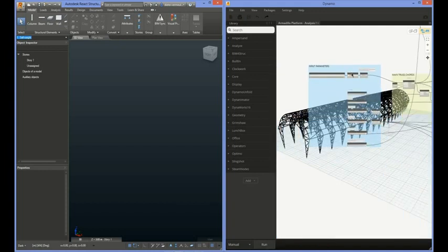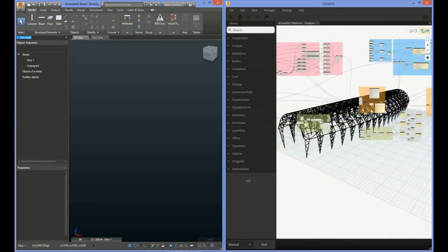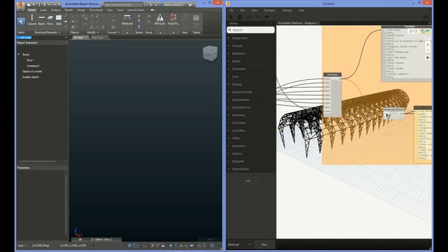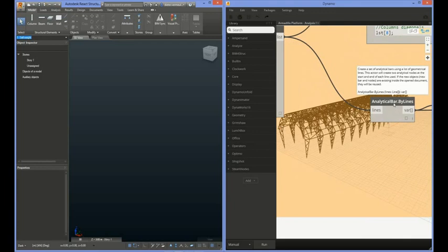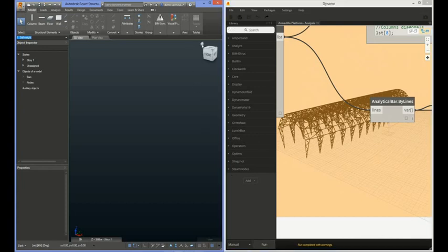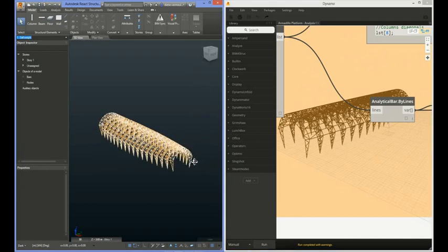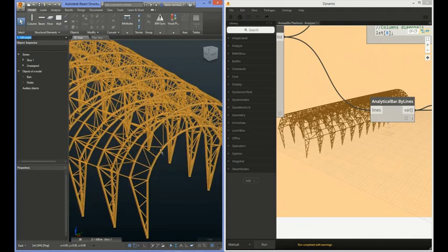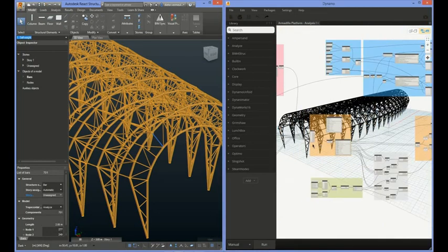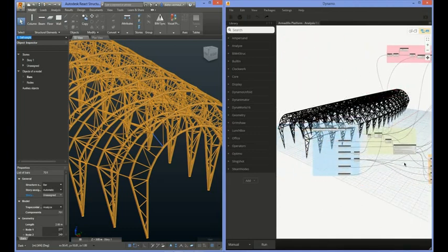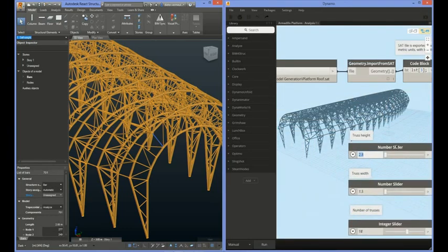So my population was very small. Normally you should start at least with 10 and make at least 5 generations, which would mean I would have 50 solutions. You would see if I run this one 50 times, then I will have variety of results, which means that I wouldn't have found an optimal one. So therefore, you can evaluate that weight score. So if I wouldn't have done anything else with that parametric run, for instance, then I would say, okay, this is my optimal solution, let's build it. But the weight score is 15,000, and I know that there are solutions with a weight score of 11,000. So this is not an optimal solution.